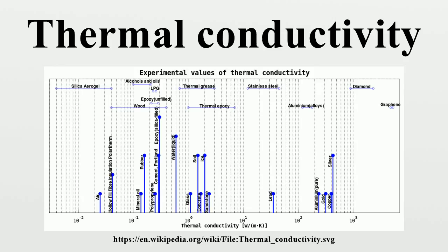often proportionally to temperature. On the other hand, heat conductivity in non-metals is mainly due to lattice vibrations. Except for high-quality crystals at low temperatures, the phonon mean free path is not reduced significantly at higher temperatures. Thus, the thermal conductivity of non-metals is approximately constant at high temperatures. At low temperatures well below the Debye temperature, thermal conductivity decreases, as does the heat capacity.